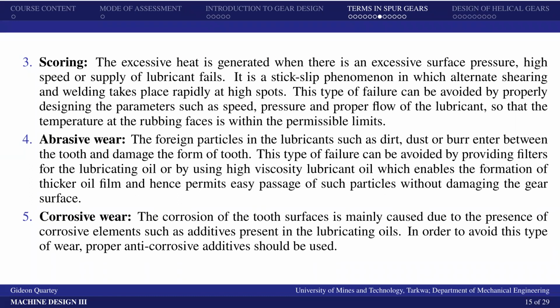Okay. Then we also have corrosive wear, and this corrosion may be caused by the presence of corrosive elements such as additives present in the lubricating oils. There are times where there may be some additives in the lubricating oil, and this may cause corrosion of the gears. In order to avoid this type of wear, the proper anti-corrosive additives should be used.